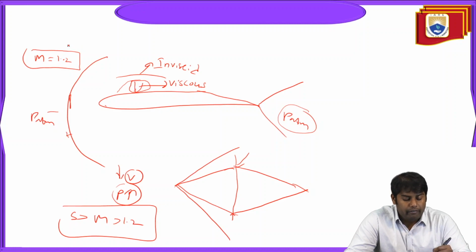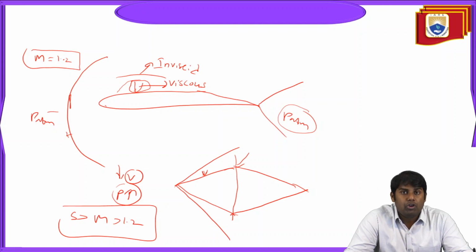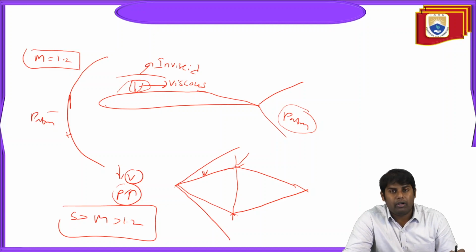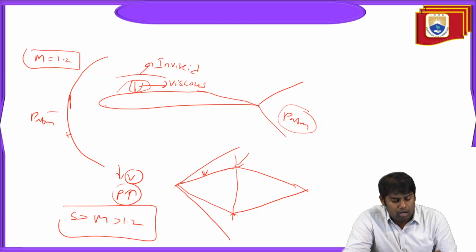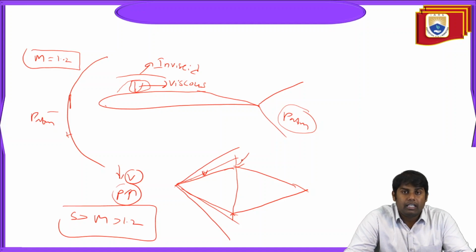Okay. So when you have the boundary layer attached to the body and the shock interacts with the boundary layer, that is called shock wave boundary layer interaction. What is happening is the flow will generate a transition. It will generate some separations, or some eddies, such that you have unsteadiness. Okay. And when you keep on increasing the Mach number, the shock will get attached to the body. It will come very close to the body, such that heating of the body will take place.